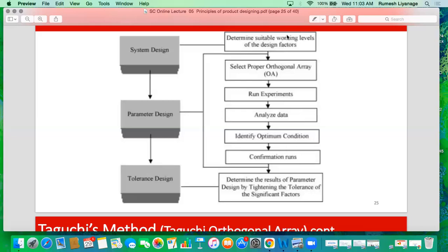Sometimes you have to use Taguchi's L4 design. There are three factors at two levels. Then how many trials are there? Can you remember? There are 4 trials, and after conducting the 4 trials, you can select the optimum one. Then confirm.